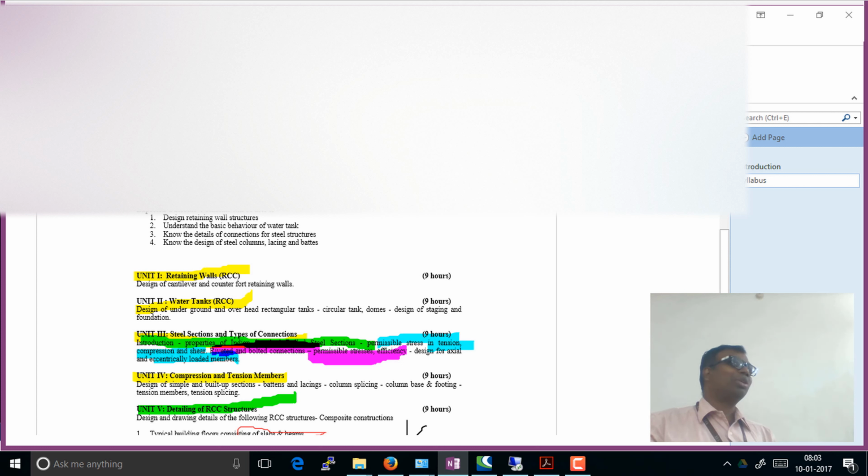There is no foundation bolt, and I have also seen structures where they would have erected the entire thing, and two rows of columns will be just suspended. There is nothing to sit on. So one way of looking at it is the fabrication is so quick and it's very tolerant to errors. Somebody didn't do the foundation bolt, but still the structure was able to stand. But of course, it's not a good practice. It's not expected of a managed engineering organization. But these are some of the things about steel that we can talk about.